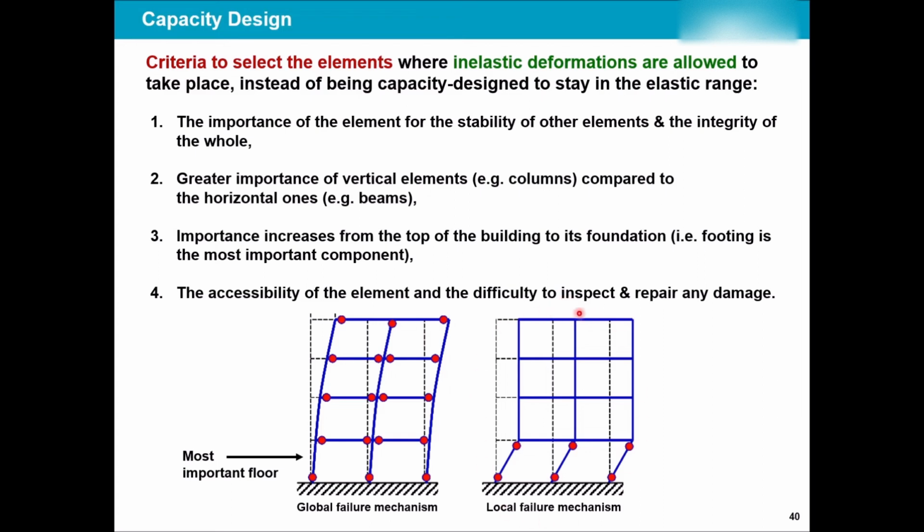This is what we saw in the Mexico earthquake. The bottom bits failed, the parking failed, because usually you have openings over here as well, and you have walls on the top. A very stiff structure on a very weak structure: the bottom bit fails, all of the structure fails. But this one is allowing the building to start dancing and dissipating energy, and if one of the beams fails, it doesn't affect the rest of it.